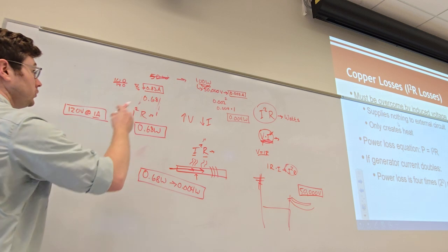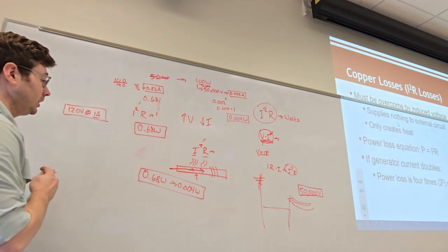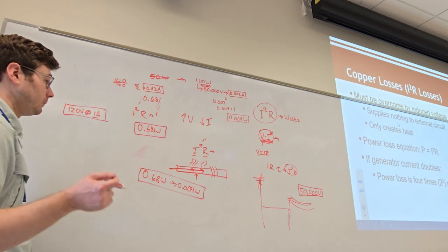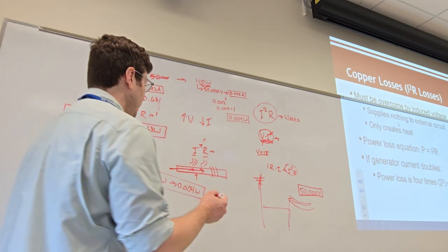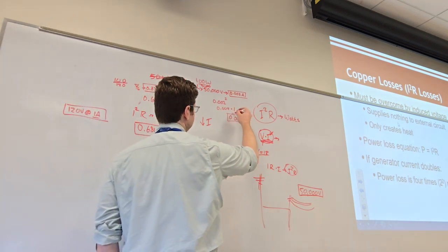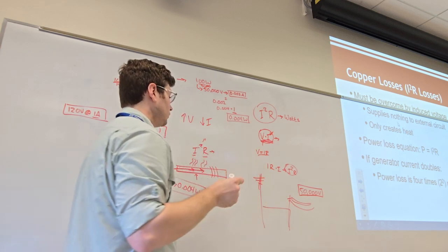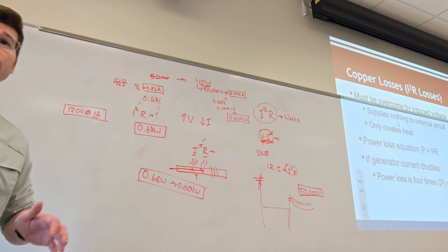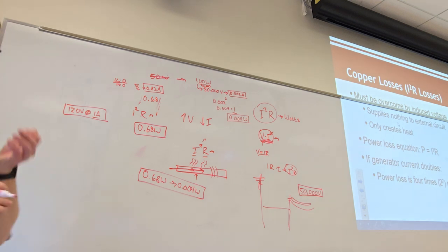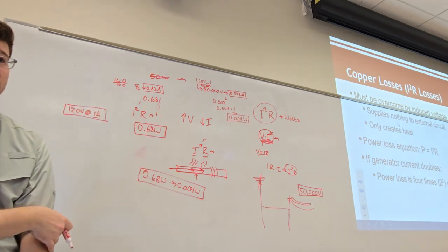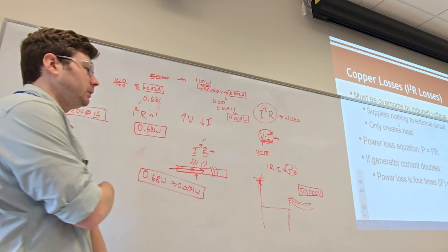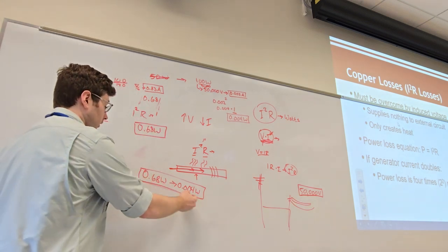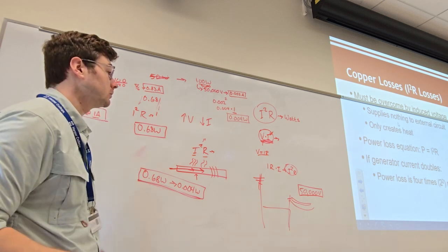If we had just used a different voltage to get the electricity down that wire, we would have a much different scenario. And 1 ohm, by the way, is very, very small. 1 ohm is like maybe 10 feet of wire. When we're talking about actual transmission lines, those things need to run for miles. The ohms on that might be in the hundreds of ohms. So we're having serious power losses across all those lines.